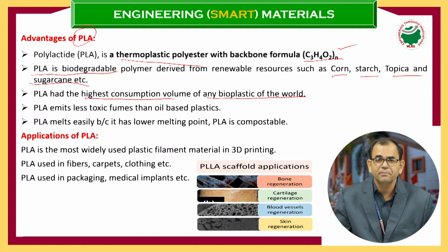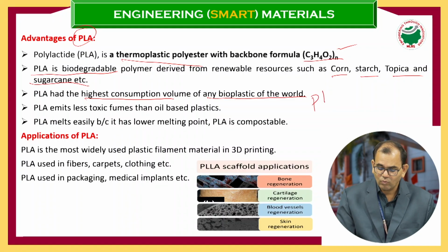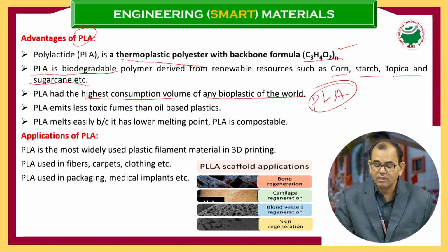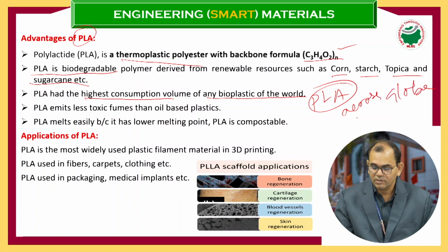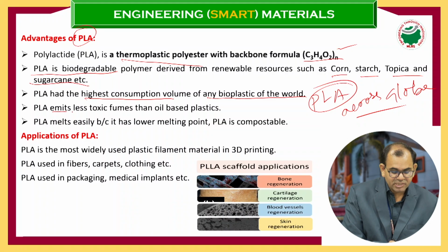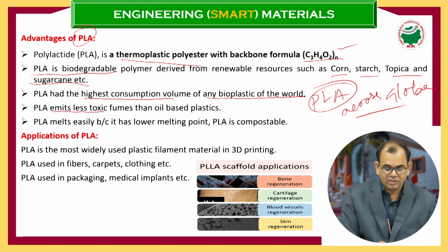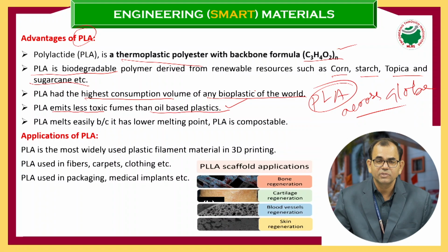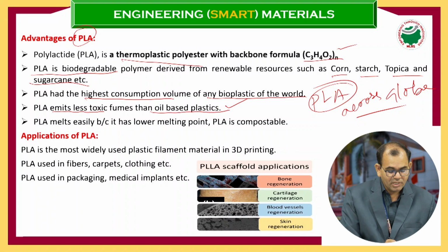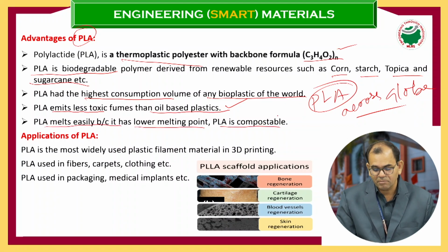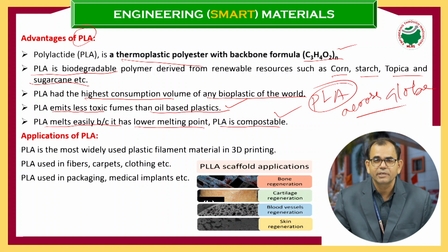Based on its biodegradability and shape memory properties, PLA is a widely used polymer across the globe. PLA emits less toxic fumes than oil-based plastics. That's also one beautiful characteristic of polylactic acid. PLA melts easily because it has a lower melting point, and PLA is compostable. Easily it can be degraded.